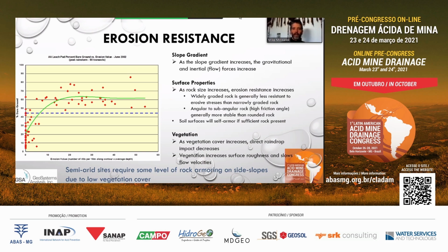And then soil surface will self-armor. So if you have a material that has rock in it, the fines will wash out and you'll leave the rock on top. Now, I just wanted to show this graph here where you have,